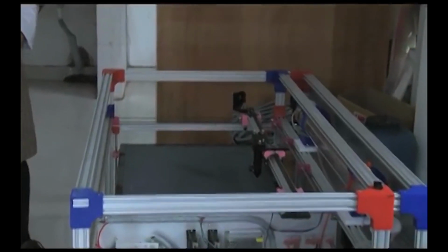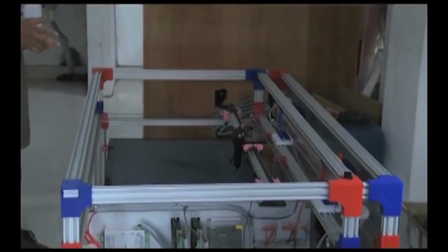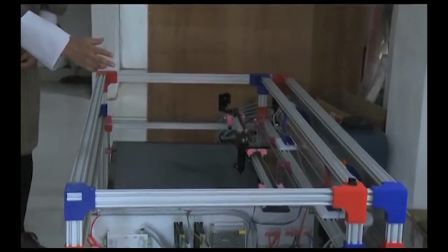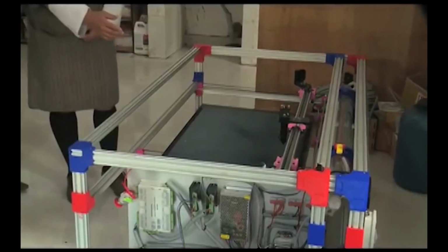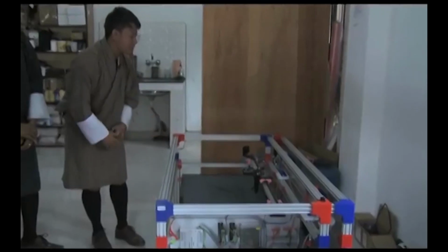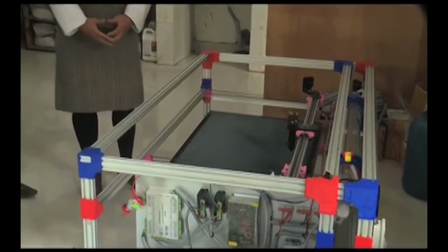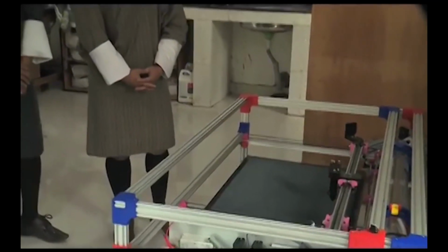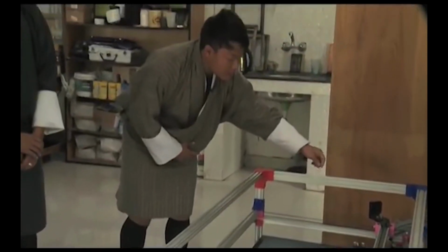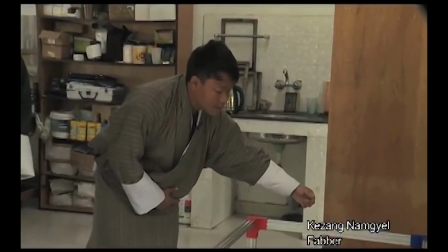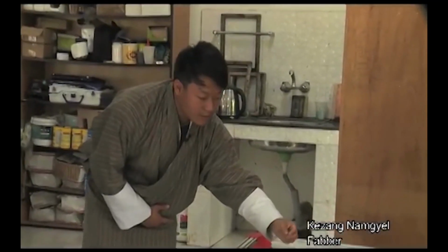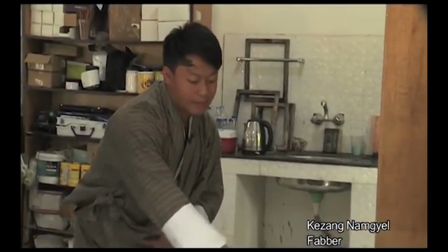We are replicating this machine of 80 watt. This machine is three-dimensional, mainly X, Y, and Z. The power that is generated is converted into laser light, and the laser light is reflected by the mirror. So it basically works on the principle of total internal reflection. It hits the first mirror down there and reflects to the second mirror, and finally to mirror 3, and finally it comes onto the surface.